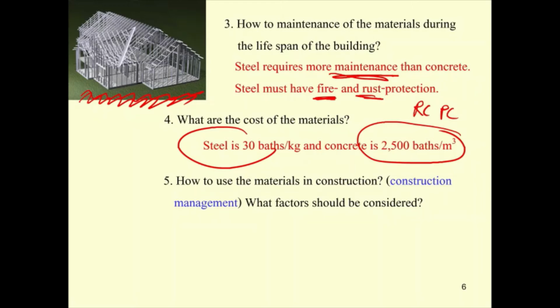But nowadays, concrete also has some kind of precast. It can be produced at a concrete plant. This pre-stressed concrete can be both RC and PC pre-stressed, and is also high quality. But its weight may be large during transportation compared to steel, and the installation is also harder compared to steel because of the weight.